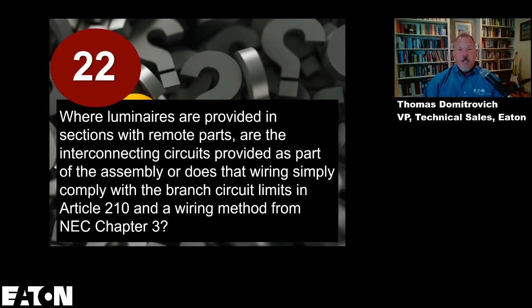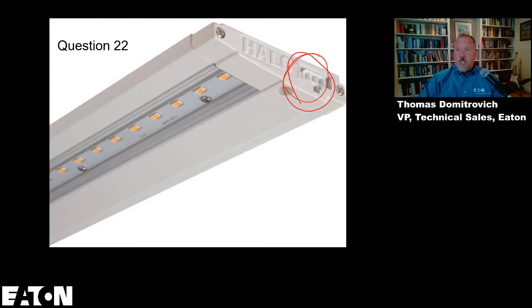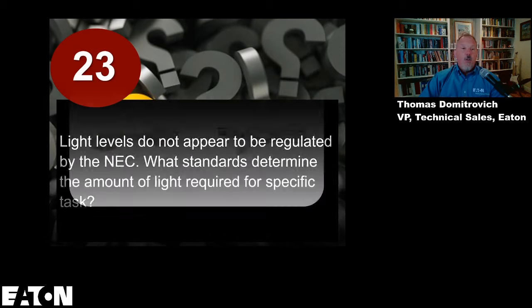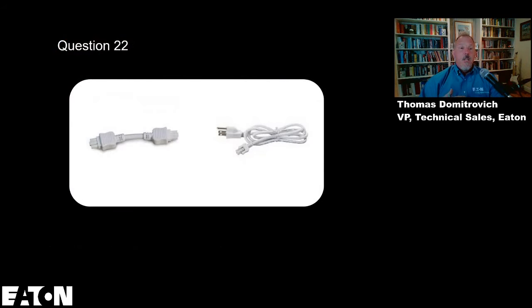And you're going to have to size the conductors correctly, protect the conductors correctly, etc. So I would make that argument that it could be either way, but to point out these types of applications here, these are all part of listed luminaires. If they're all part of the listing, the wiring methods that are used are all basically based upon the listing, and as long as you are applying that product within its listing, then you are good.